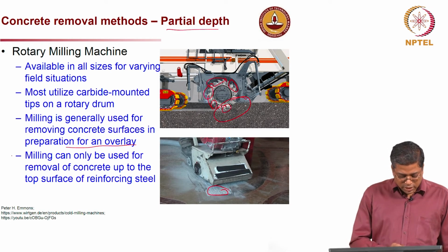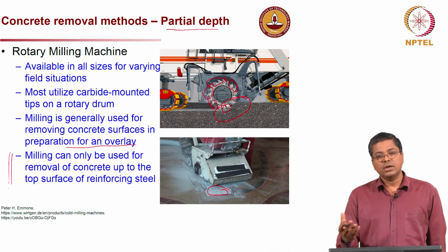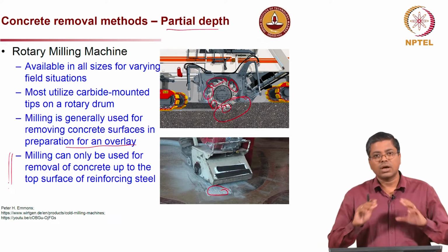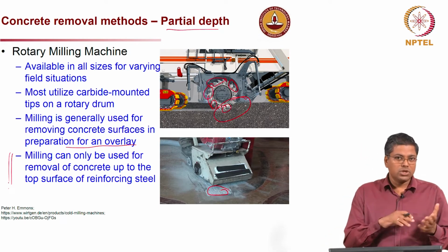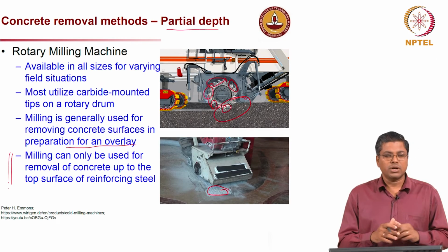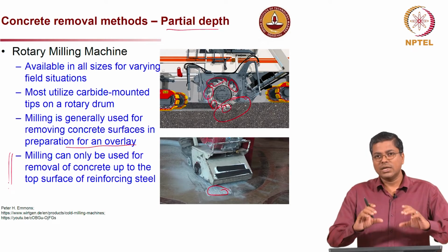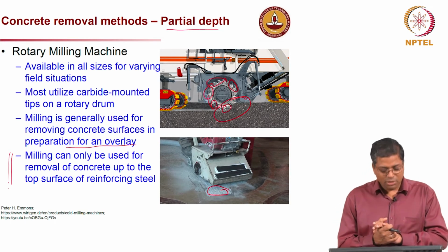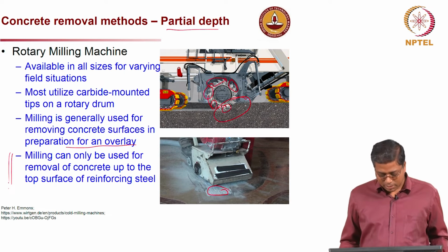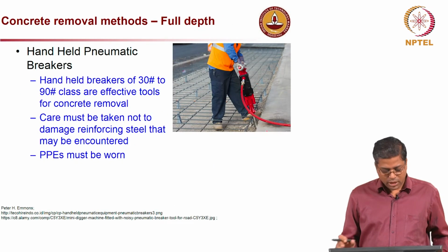And one thing is, you cannot mill beyond the cover depth. So if the cover depth is non-uniform, then it might be a problem in using this type of tool, but if the cover depth is uniform, or at least the cover has some minimum value, then up to that depth you can go for removing concrete.